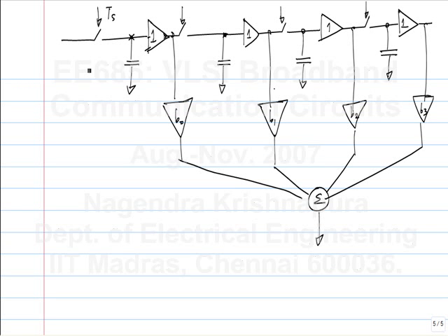What are potential problems with this? Summation block. How do we implement it? We'll see that soon. But we can do it like we did before, right? How did we do it in case of the transmitter? Sure, you need linearity. Whereas before you could use transconductors in their switched regions, now you need them to be linear. That is, the output current must be proportional to the input. But besides that, you can use the same approach: a number of transconductors connected to the same output nodes. So the currents sum, and then that passes through a certain load impedance.